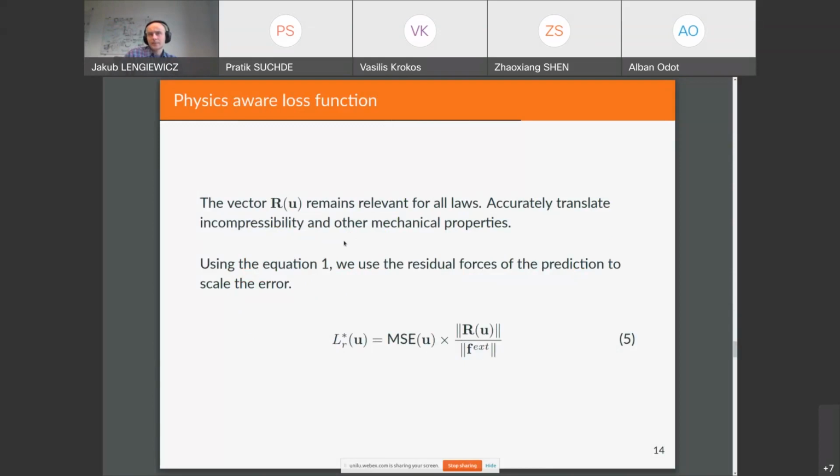Yes. So basically, when we compute the solution of the Newton-Raphson algorithm, we compute this right-hand side member, that is the residual forces, the difference between internal and external forces, and we know that this vector reaches 0 when we reach equilibrium. So the norm of this vector is actually a criterion of the solver.